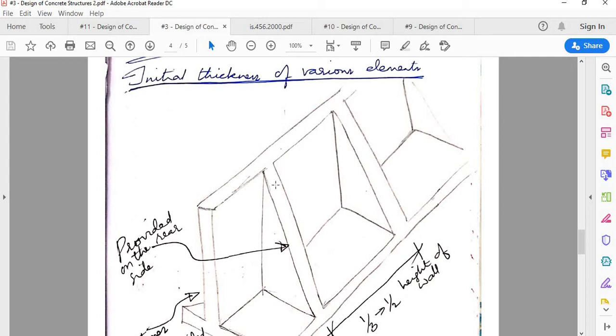You can imagine this counterfort carrying some portion of the top portion of the vertical stem, and the same portion is extended throughout its depth, whereas this portion is increasing in size. So you can imagine this as a T-beam of varying depth.